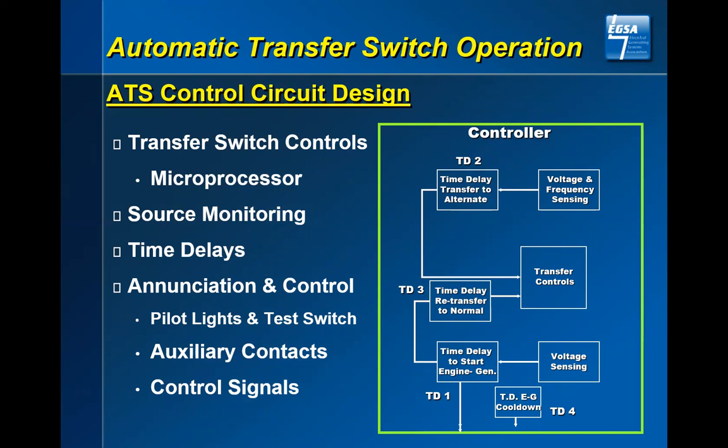An example of that is that typically with a transfer switch, you will have a switch position set of lights. We're going to see one of those shortly here. And you will also have a set of contacts that will tell you whether you're connected to normal or emergency. You may want to know that at your control station. However, you will have a set of lights to tell you that either your normal or your emergency is available, but you will not have the auxiliary contact stating that unless you pick that up.